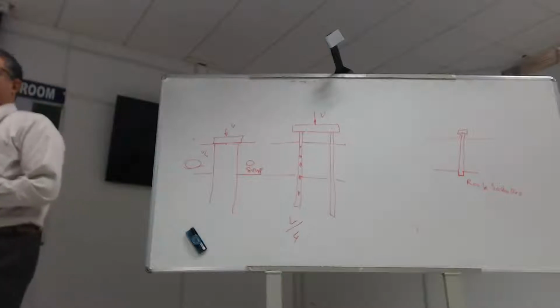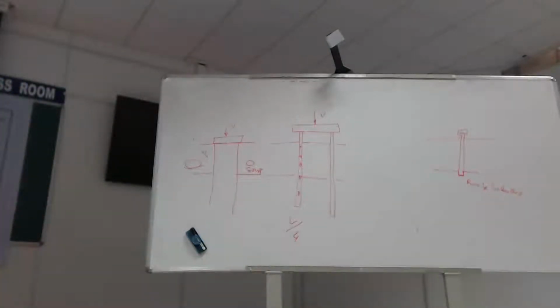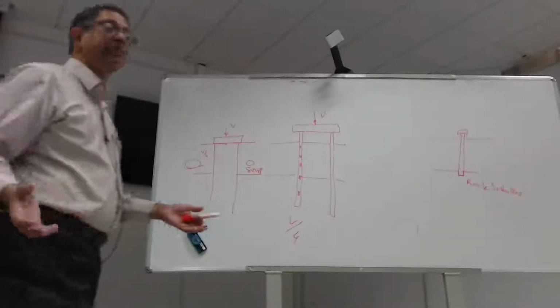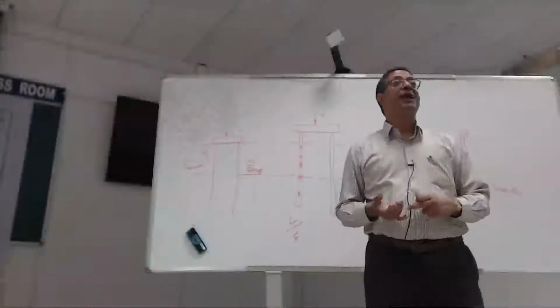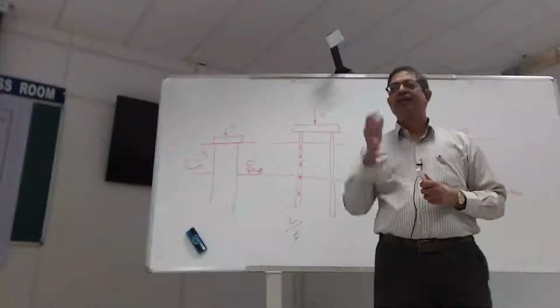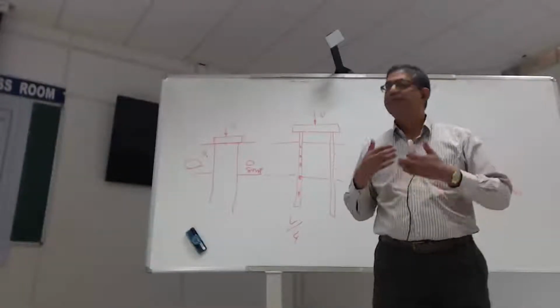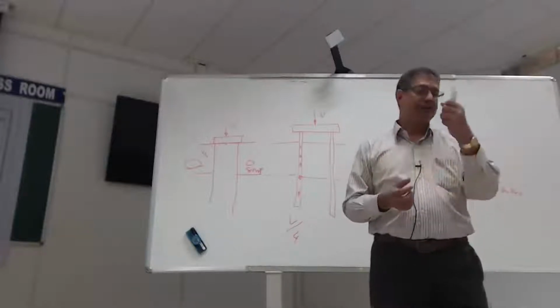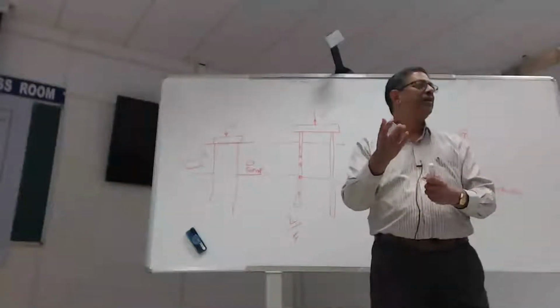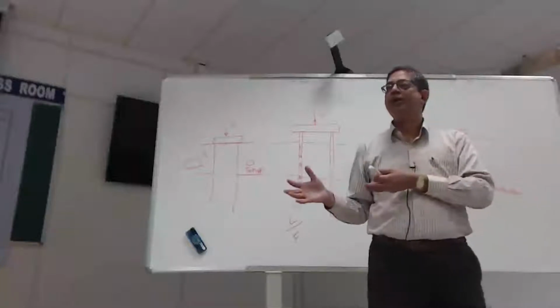So the pile cap capacity, ignored worldwide, is the one thing that is saving these piles. If not for that, more buildings would have collapsed in all the past earthquakes. It's just that we don't know. And not only do we not know, we deliberately ignored it. So you can see why we need more research into understanding how the pile shaft, pile base, and pile cap share loads in different loading scenarios.